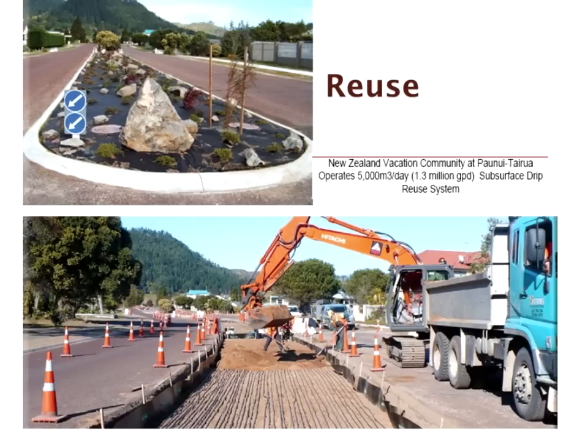When you do a reuse system, you have extra factors involved. Either you're going to have the right amount of water to balance evapotranspiration at the maximum rate of evapotranspiration, then during the rest of the time you have to have an alternative disposal field to get rid of the surplus water.